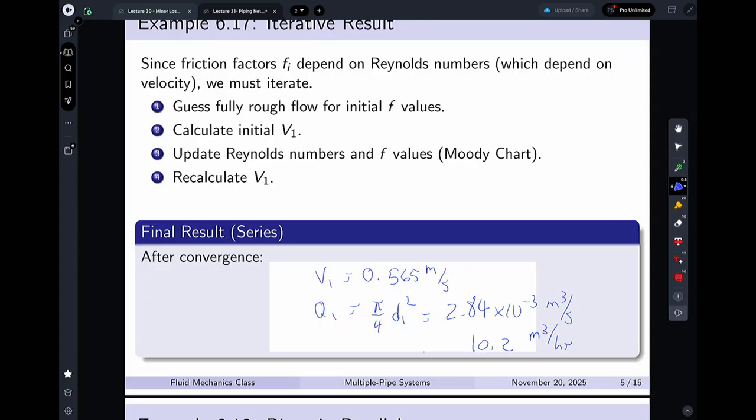Any questions on this? What are the alpha terms again? Are you just simplifying the expression for major loss? So I know alpha 1, alpha 2, alpha 3, it's just f L1 over D, and I can just multiply across. I can get rid of all of the terms in that case. So I shouldn't have written it that way. So alpha is that whole expression, the whole term plus a proportionality to deal with V1 squared.